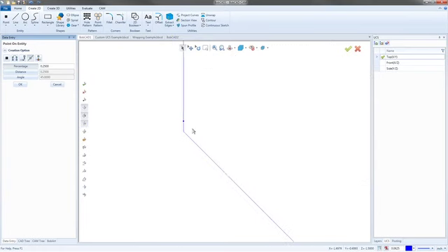And what's going on, it's not actually at the end of the line. It's a quarter of 1% up the line, because the problem most people do is I don't work with whole numbers very often. If I do, it's going to be ones and twos for 1 inch and 2 inch and stuff. But when I'm defining tools and I'm defining radiuses and I'm just defining these decimals all the time, my hand just automatically types 0.25 instead of 25 like it's supposed to.